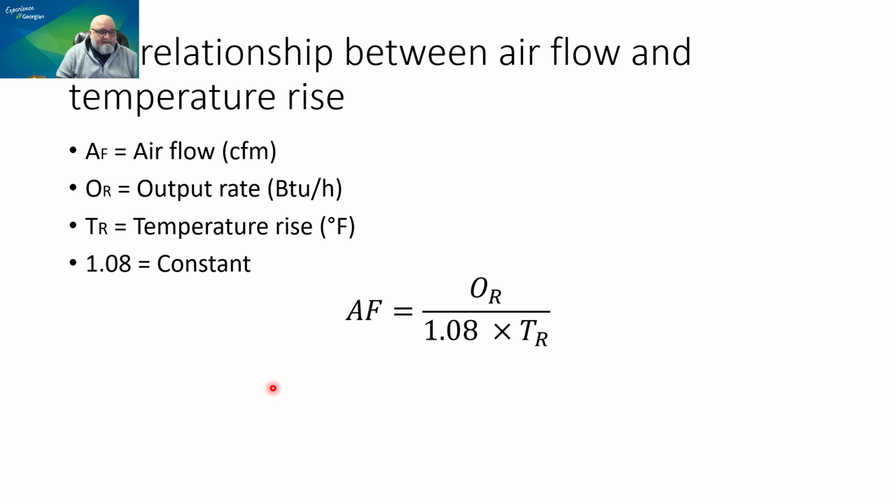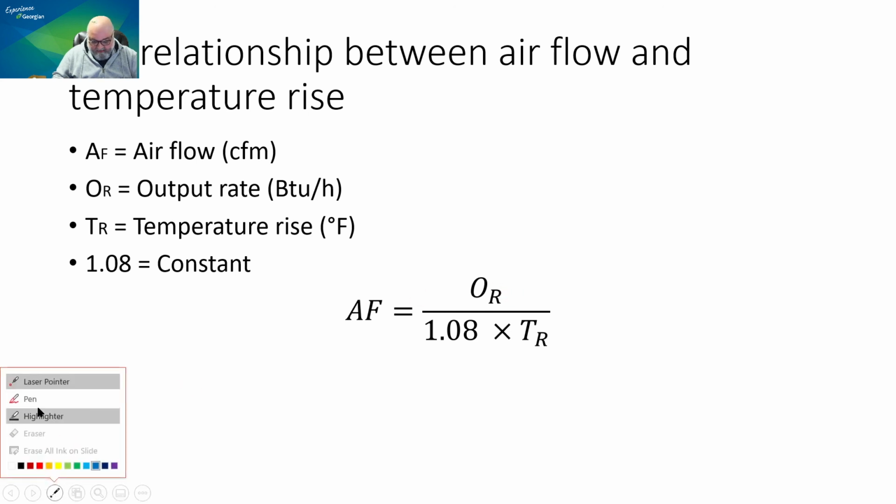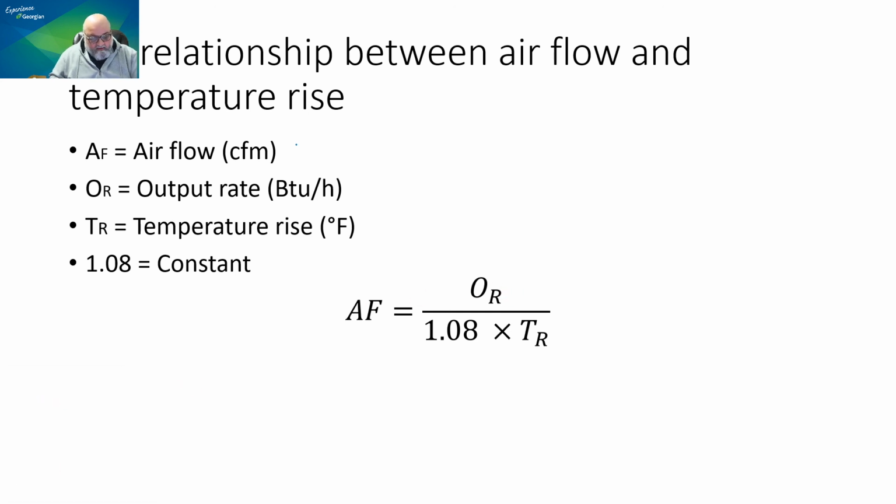This is something that's going to be one of your troubleshooting instances. So how do you go about finding out what happened? Here's a simple example. This is what you're going to calculate. Why? Because I just told you it is 80,000 BTUs per hour. It requires 2,000 CFMs. Okay?